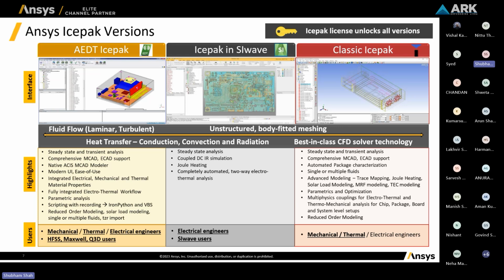In a similar manner, you have comprehensive MCAD and ECAD support. When we say MCAD, it's mechanical CAD, and ECAD is known as electronics CAD. So we can import the geometry from SpaceClaim into Icepak Classic. We need to perform certain operations in SpaceClaim to convert the normal mechanical or fluids files into the Icepak Classic files. Then automated package characterization is available, single or multiple fluids.